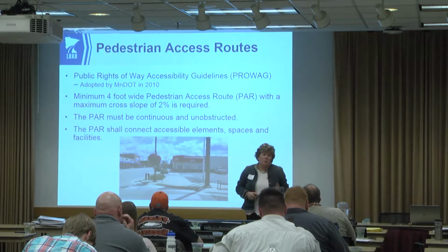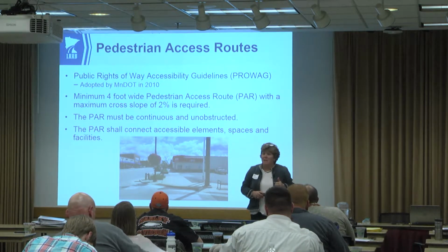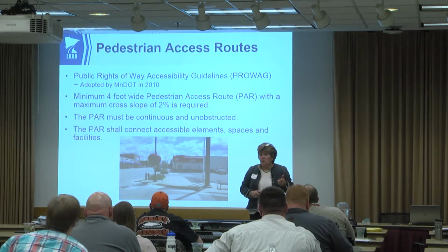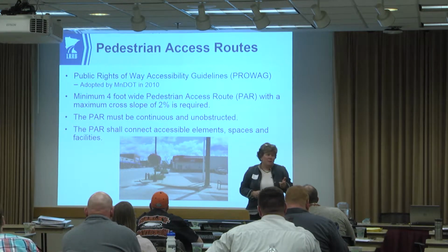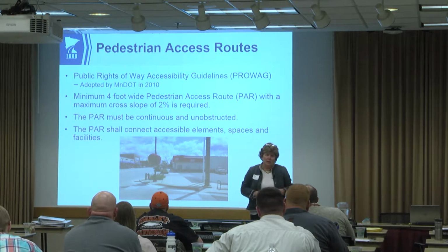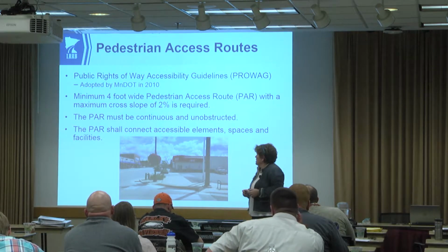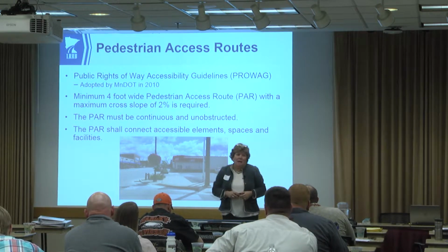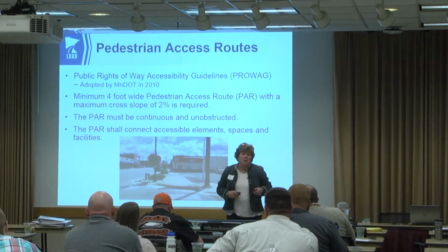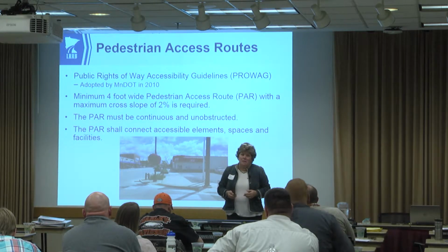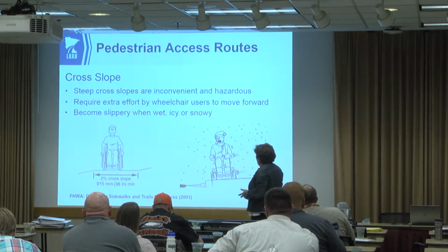The overriding principles as we go through these are pretty easy. Cross slope must be maintained at no more than 2%. Longitudinal grade at no more than 5%, and if it goes up to 8.33%, we need to consider a landing and other provisions. And I think that's about it. Those are the two big considerations. We also have to make sure to provide a landing when a change in direction is part of the ramp condition, and when we have a cross or a longitudinal slope that exceeds 5%. So with that, we're going to dive right in.